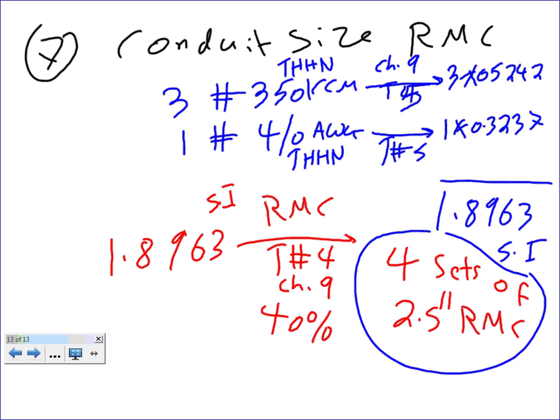No. We're going to use EMT everywhere above ground, PVC underground, anything service rigid. PVC schedule 80 for the service, PVC schedule 40 for anything underground, above ground EMT in our project. That's the best way to do it, I think.